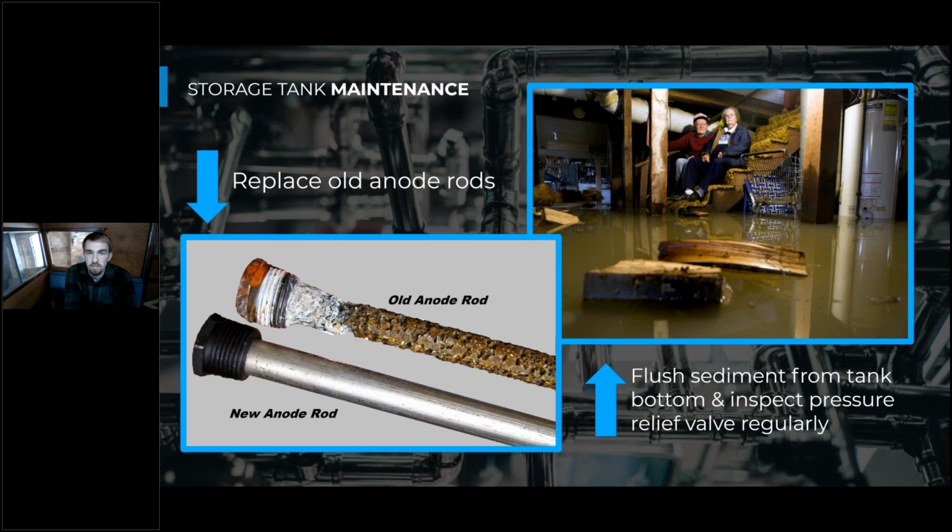So this could, first of all, be dangerous to anyone around the tank, because any really high increase in pressure that was not anticipated now cannot be safely removed through that pressure relief valve. So that turns into either the tank or the pipe surrounding the tank rupturing.